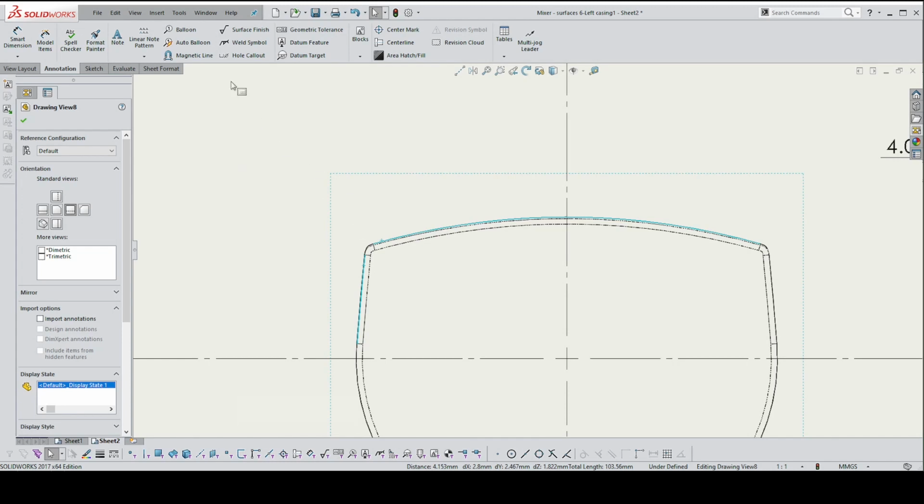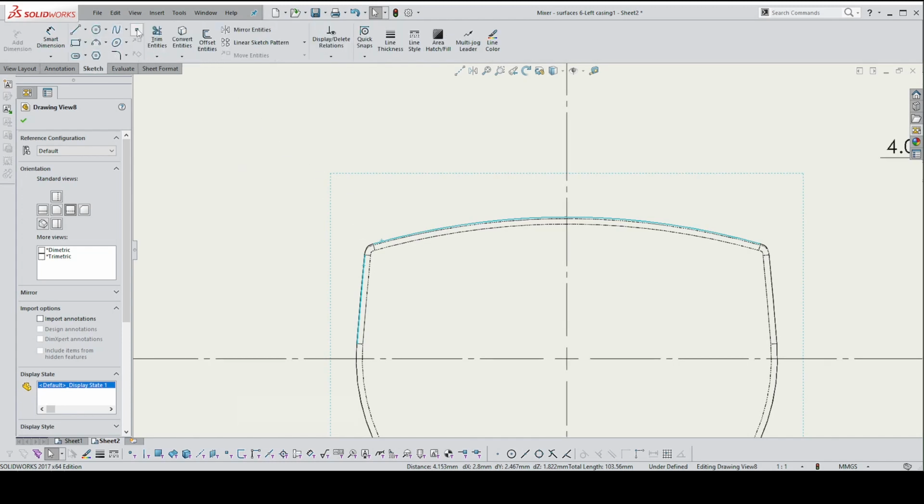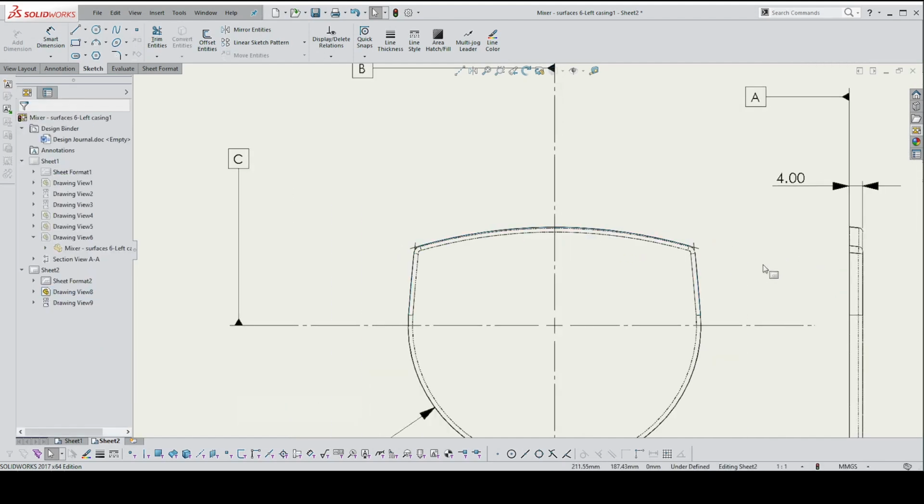So select the two lines by holding the Shift button down, go to the Sketch key and put in a point. You will get what's called a virtual sharp. If I do that again, click on a line, shift select the next one, or control shift the next one, putting a virtual sharp. Okay, so that indicates the end point of where those two planes would meet.